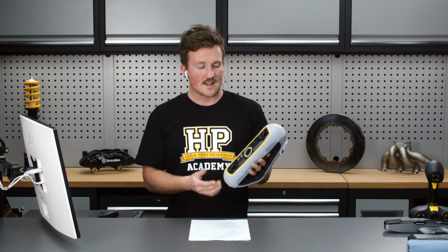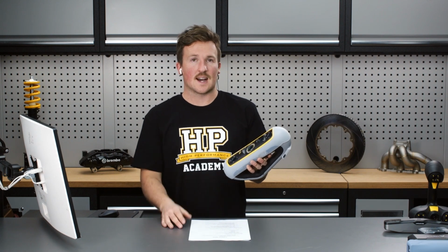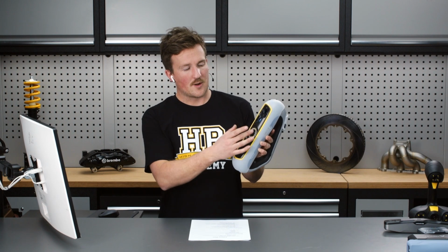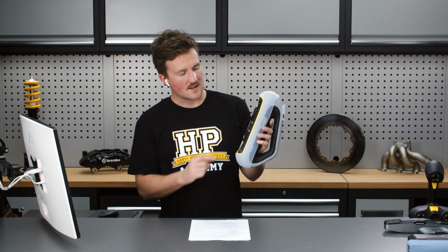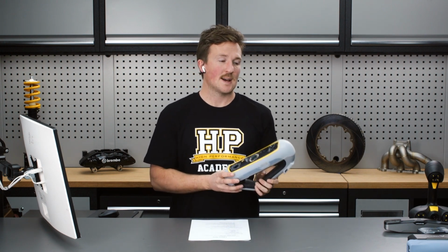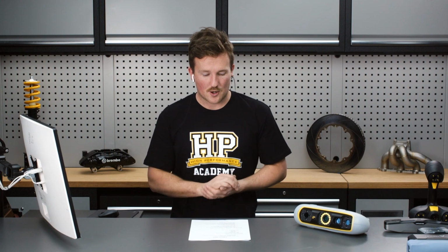So with structured light, it's the same idea. Rather than using a laser, it's just using a structured light pattern from the central projector here. In this case, all these LEDs around the outside are just projecting a light pattern onto the surface, and that light pattern looks a little bit like a QR code or something like that. Depends on the scanner you're using. It's just a complex pattern, and then the cameras can use the triangulation to view how that lands on the surface and deforms, and from that it can build the 3D model.